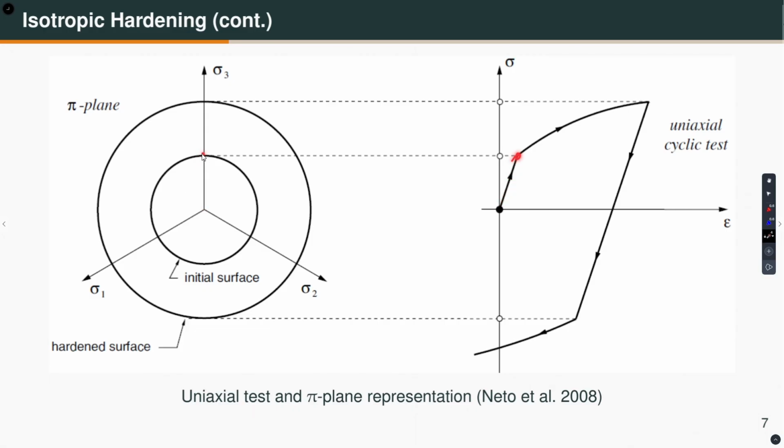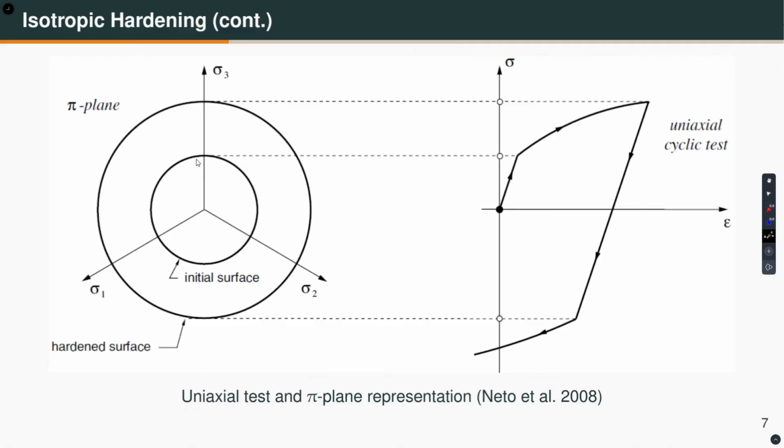The moment the point reaches the yield surface, then it starts to grow. Now, that nature of growth of the yield surface can depend linearly on the plastic strain, or non-linearly. We are not getting into those discussions, but it can be linear as well as non-linear. So, when that growth is non-linear, then from here to here you can get a non-linear relationship.